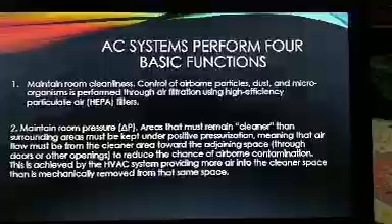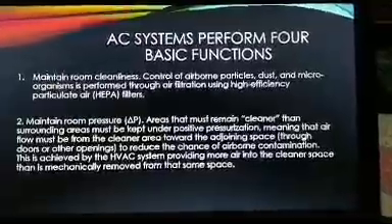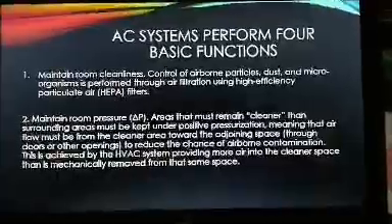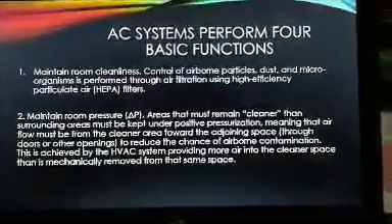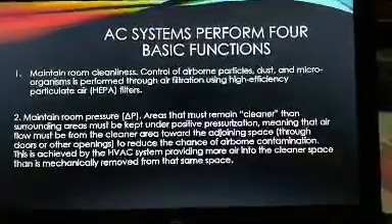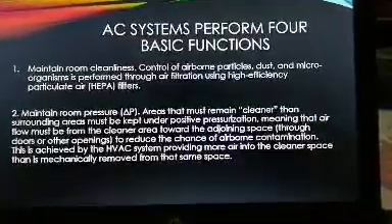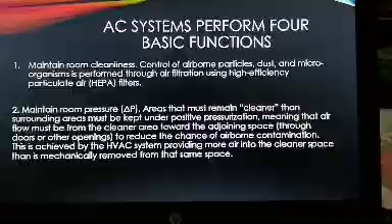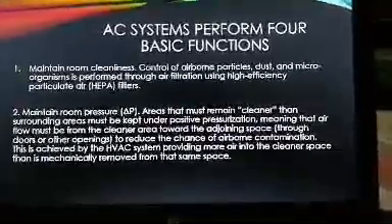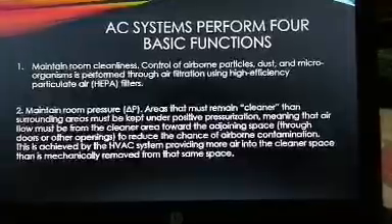AC systems perform 4 basic functions. 1. Maintain room cleanliness. Control of airborne particles, dust and microorganisms is performed through air filtration using high efficiency particulate air (HEPA) filters. 2. Maintain room pressure delta P.